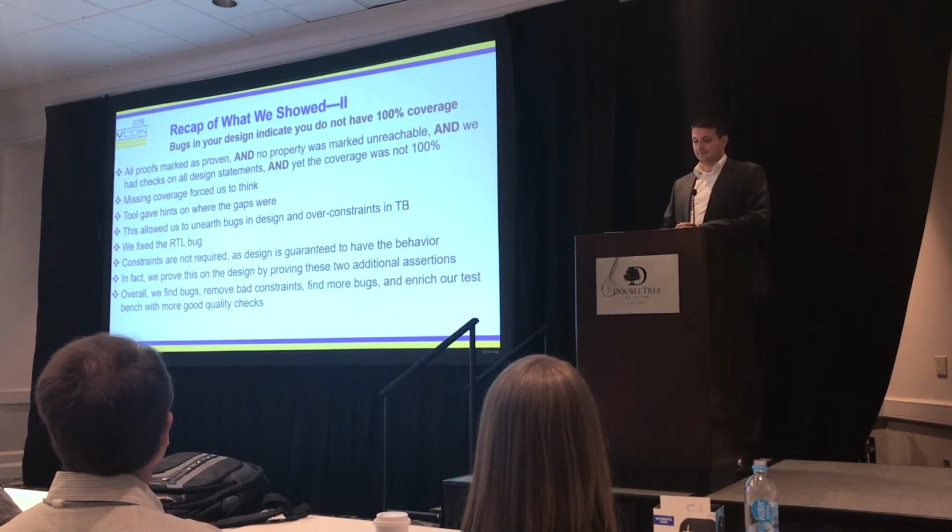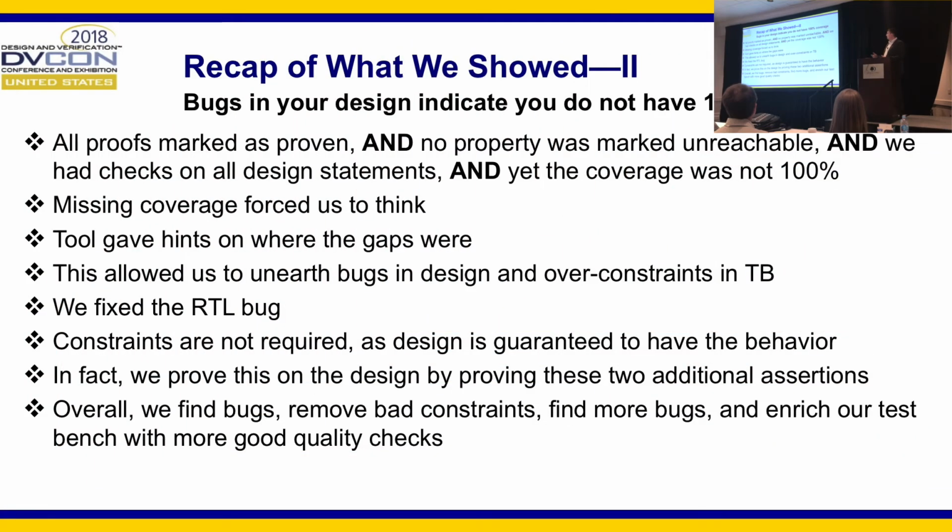Okay, and if you do have bugs in the design, it's very obvious you don't have 100% coverage. So what quantify is able to do for you is it can force you to think about the checks you're missing. It can force you to think about the environment you created using the constraints, whether you're over-constrained or not. It can guide your verification effort and give you a clear metric of how far down the road are you with your verification.